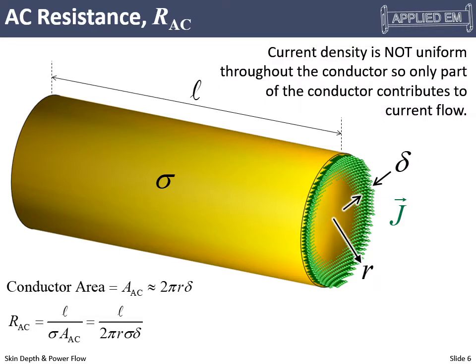So now at high frequencies, the wave penetrates into the metal but decays very quickly. And if we were to try to visualize the current and how it's utilizing the conductor, this is the way it's visualized. Notice the current is strongest on the outside of the conductor, and it decays moving away from the surface. And then, of course, we're characterizing this penetration depth with the skin depth. So really, the current is not utilizing the entire conductor. This inner part of the conductor is not being utilized at all.